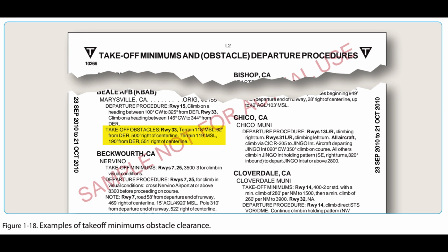This can be accomplished in a variety of ways. 1. The pilot may be able to see the obstruction and maneuver around the obstacles if necessary. 2. Early liftoff/climb performance may allow the aircraft to cross well above the obstacles. 3. If the obstacles cannot be visually acquired during departure, pre-flight planning should take into account what turns or other maneuvers may be necessary immediately after takeoff to avoid the obstructions.